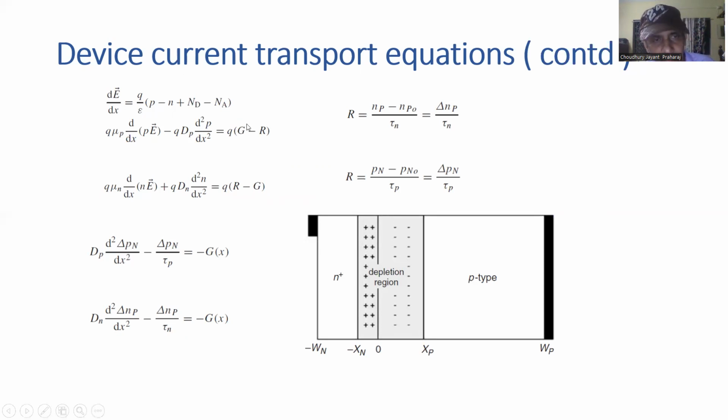And so one basic material physics is the absorption coefficient that determines the various generation rates as a function of position in these materials. Then we, of course, have mobility and diffusion coefficients and recombination rates that are also material parameters that also vary with material composition and with the material system. And that needs to be kept in mind while designing these devices, while optimizing these devices to get maximum solar cell conversion efficiencies.